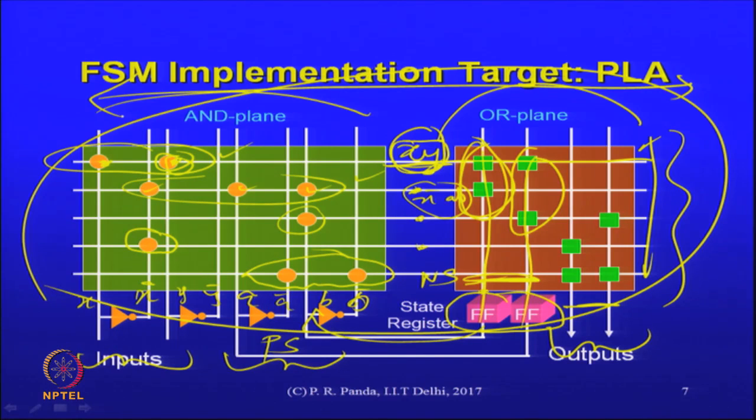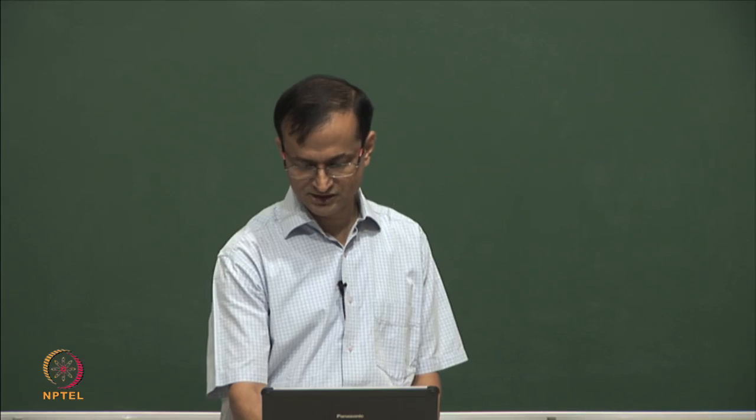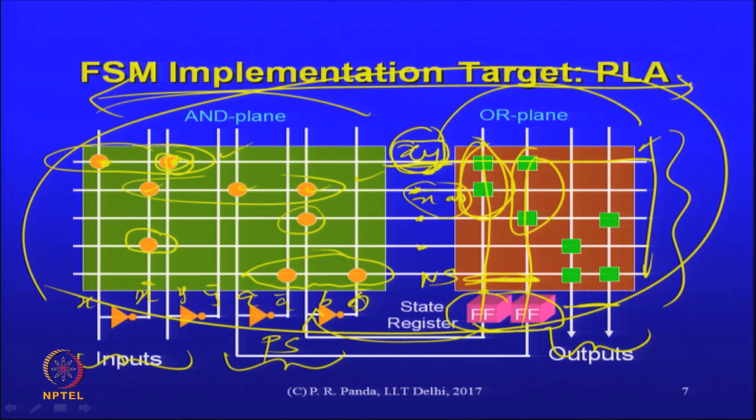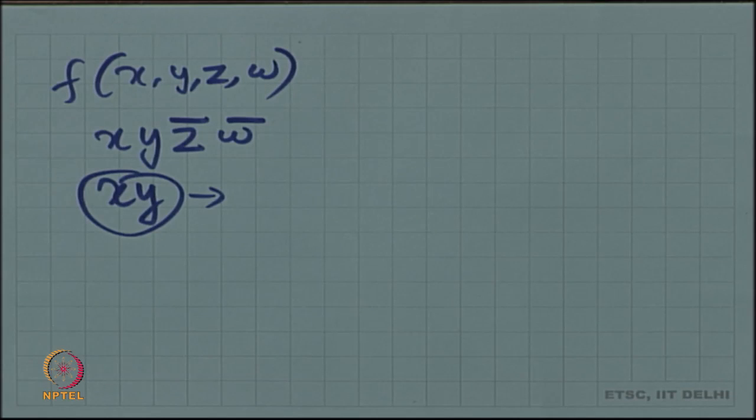As we discussed earlier, for the state register, if we use the minimum logic for that. Yes, I have some flexibility here. If I use more bits, then I have more columns for the state register. So if I just want to minimize area, perhaps I can just use the minimum number of bits. But there is a problem, because if I use an exploded state register, then my number of product terms can reduce. If I use fewer bits, then my distinct product terms can increase. So that is where the optimization angle comes in.